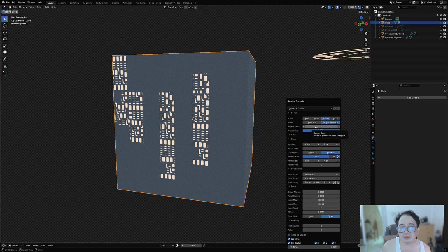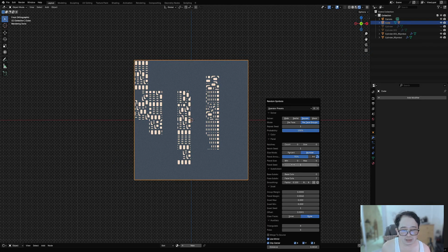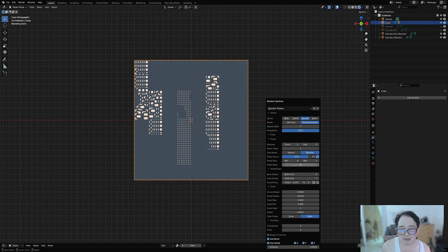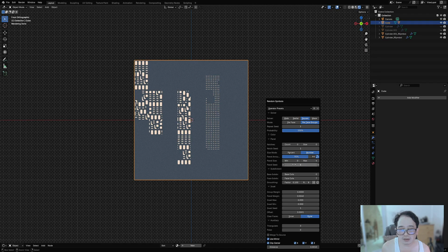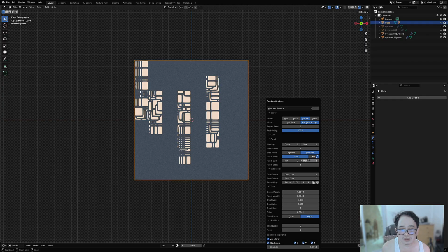So if you only have like 1 or 2 or 3 face groups, then this probably won't work so much, because it needs to have a lot of face groups or faces for the repeating pattern to actually show up. But it can still show up probably, and it all depends on the structure of the faces and also their number. Just increase the panel size to get rid of the small dots.